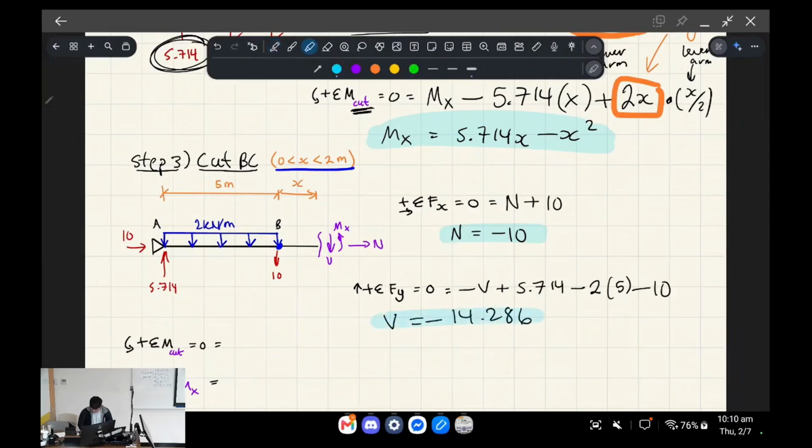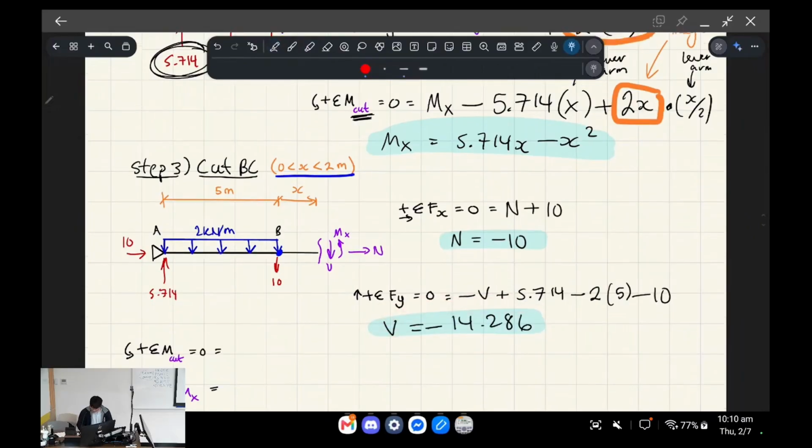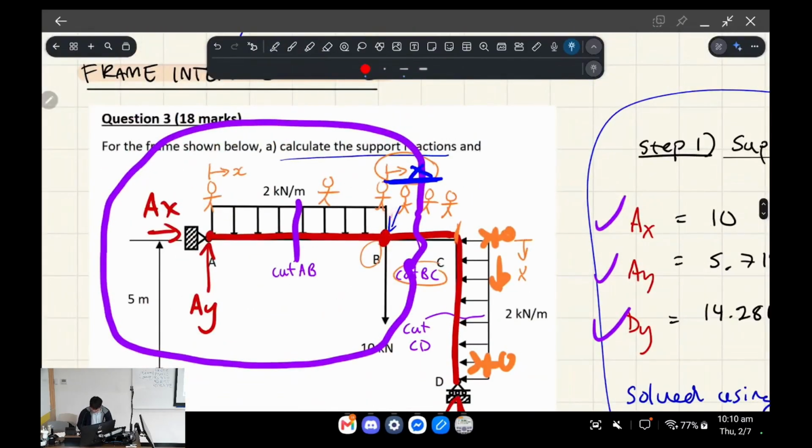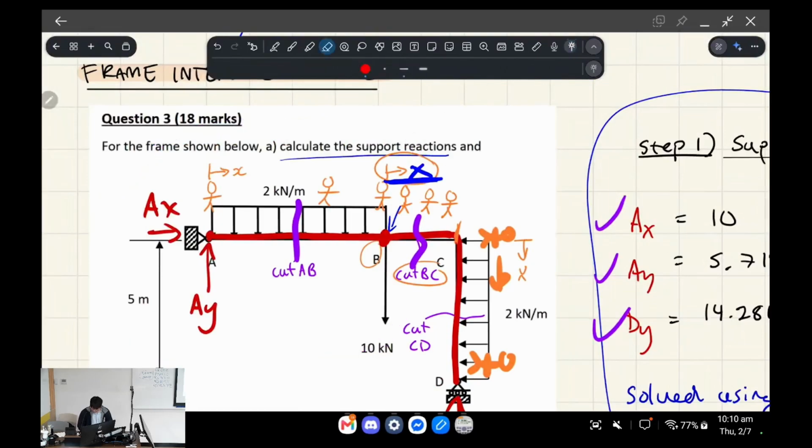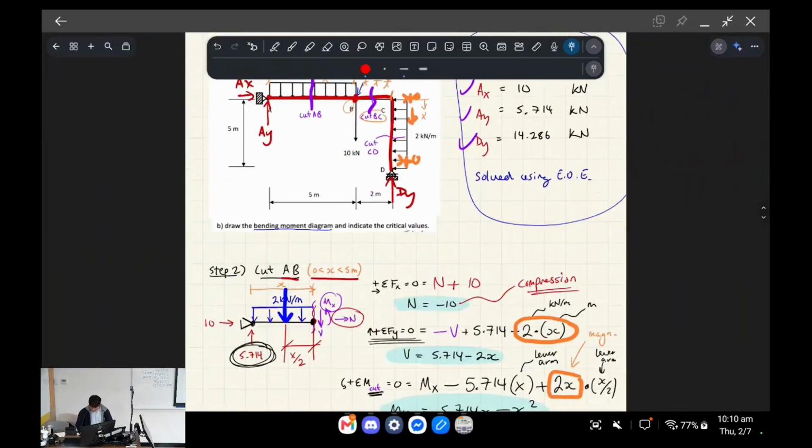Okay, what does this tell us about the shear force? It tells us that the shear force from region B to C doesn't actually change. There's no change in shear force. And that shouldn't be surprising because from A to B, there was a distributed load, which has a continuous change of the shear force. But from B to C, there's no distributed load acting on it. So therefore, the shear force graph is going to be flat, all right, at that set value.